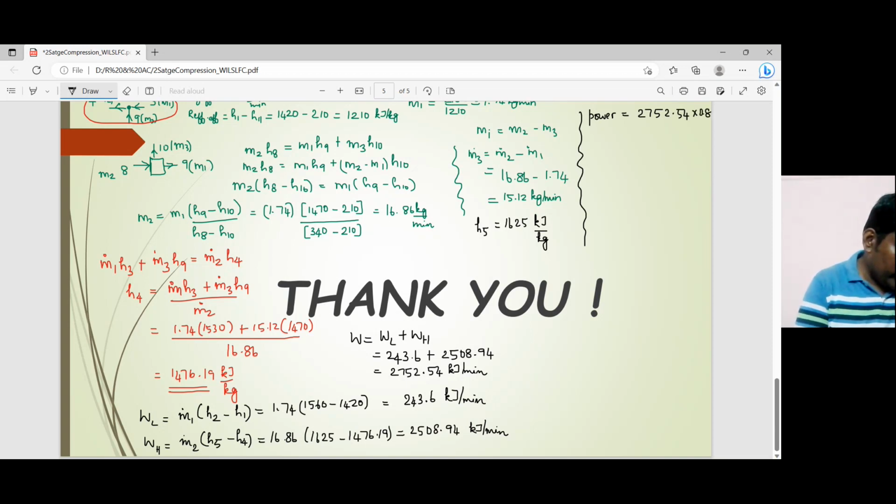If I multiply it with 0.8, I would get, where is it? I should divide it by 0.8 because when I say the mechanical efficiency is 80%, the power input should be more. Okay, so 2752.54 divided by 0.8 is